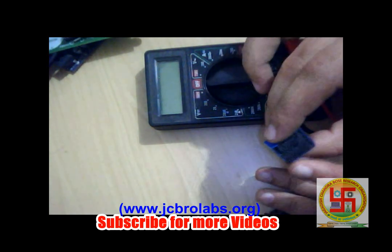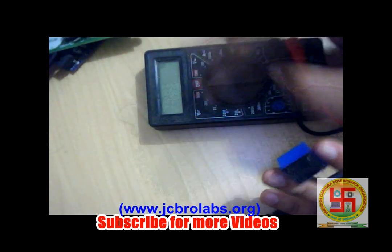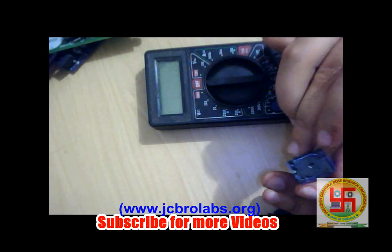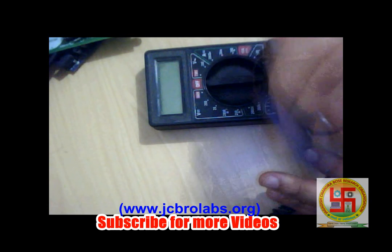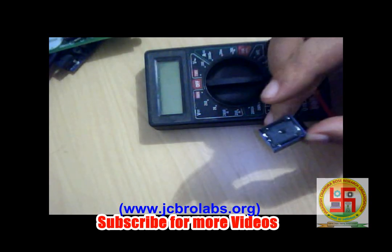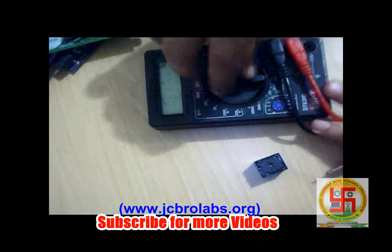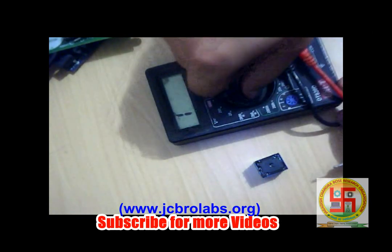Further, there are several pins for this kind of relay. For other kinds of relay, there could be fewer pins. On these 2 pins, we need to provide connections, and on some of the other pins we need to connect the different circuit which needs to be switched on and off. In order to understand which pins are connected to where, we check through the continuity test with this multimeter.